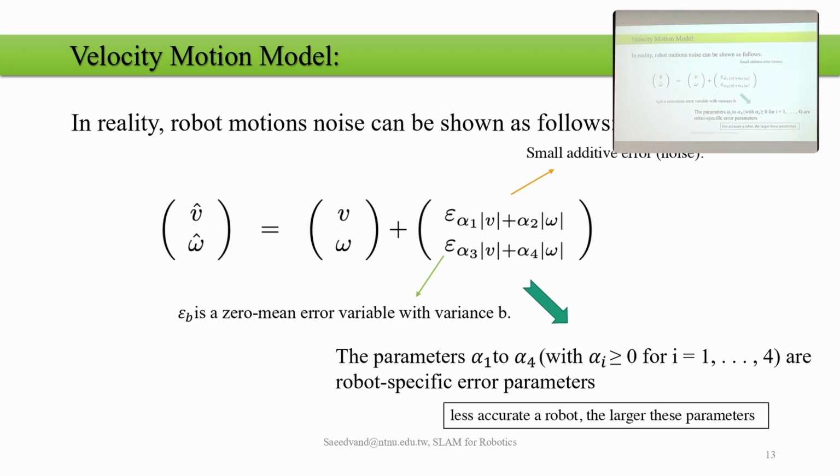1 is maximum speed. So if we put 1 here, it is the maximum speed of moving forward. If it's -1, it is the maximum speed of moving backward. 0 is like being stable. And W is based on the rotation to the left and right, with maximum or minimum. We have these values that we already know. We send them to the robot to run, and based on that we saw how we can calculate on this circle where the robot finally is. And now we are adding the error, adding error on V and W, over here and over here.